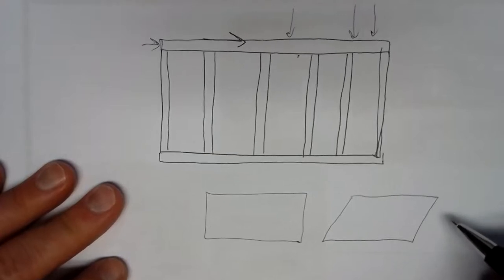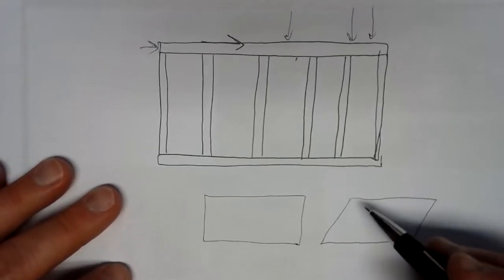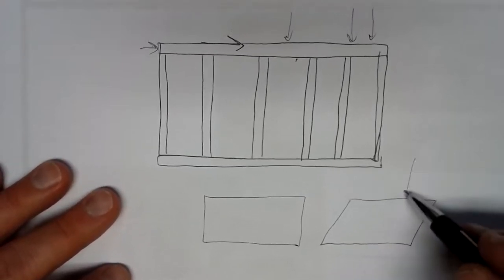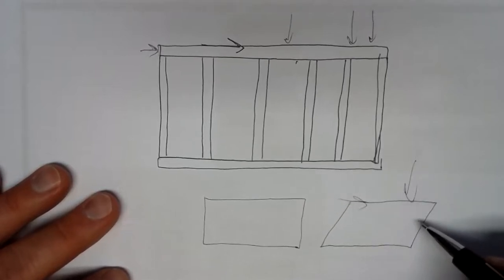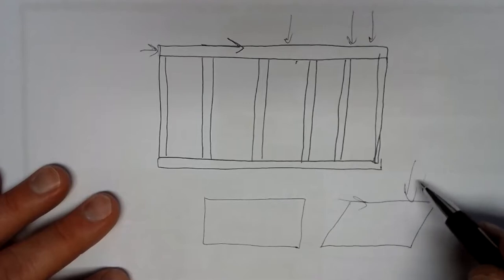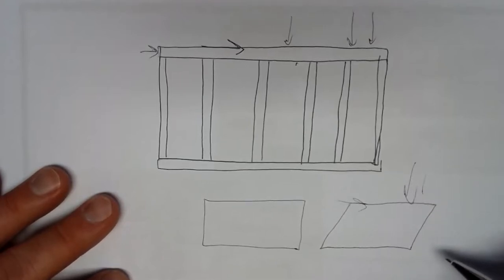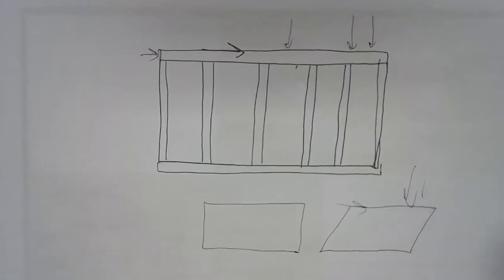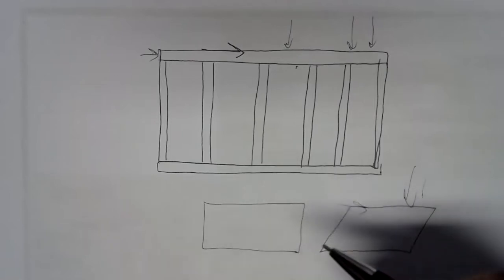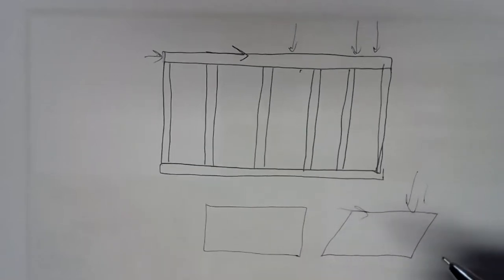And if that kind of motion gets going, if there's nothing to stop it, it can collapse. If you've got a lot of load on top and this shear loading starts happening and you get this racking action going on, then the weight that's on top can just keep driving this and it'll eventually fail. You might have seen even situations where somebody's got a roof structure put together, they've got load on the structure, and maybe wind pushes things over to the point where the whole structure collapses. Well, we avoid this by putting in panels that can resist shear.